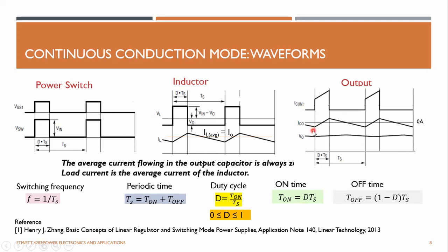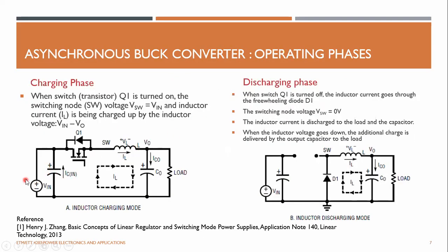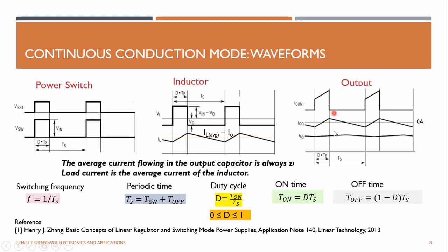And so this is the input power source, the battery current. When the device is turned on, the inductor current should be supplied from either this capacitor or from this battery. Assume there's no capacitor, which means the battery is providing this inductor current, right? That is this current. And so the capacitor current increases when the inductor is charging, and when the inductor discharges, it is decreasing.